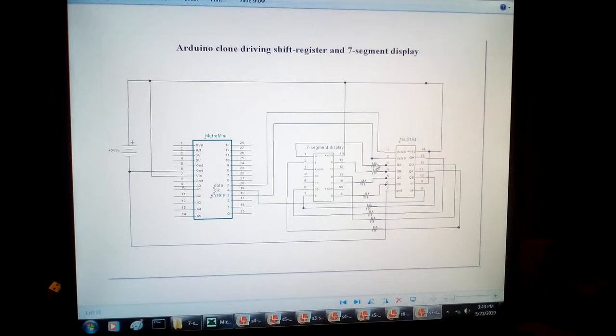Basically, the LED segments are diodes, and you're driving them in the forward direction. So if you don't limit the current somehow, you can actually burn the segment out, which is why you will notice in the demo coming up on the breadboard, there is no decimal point. Oops.